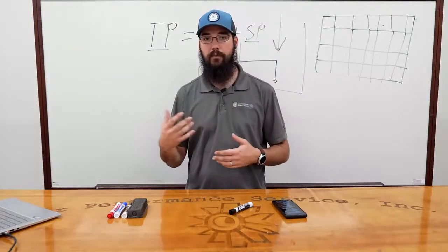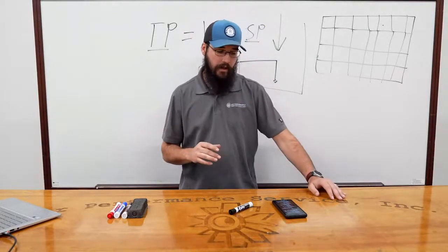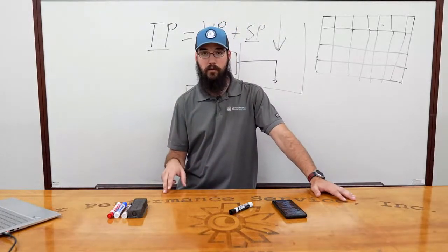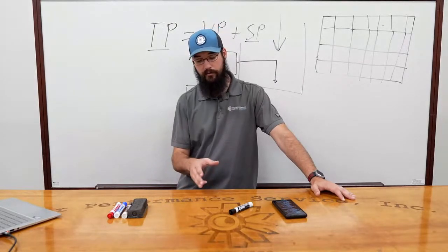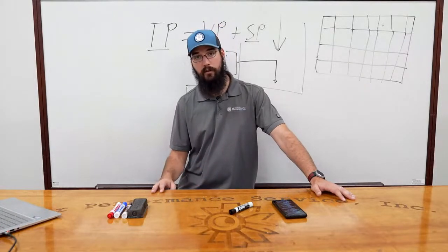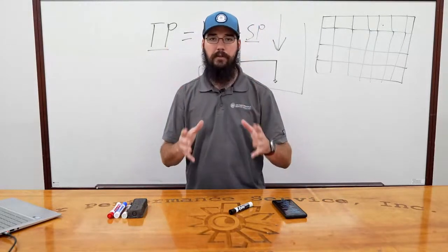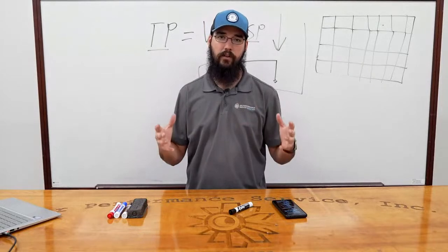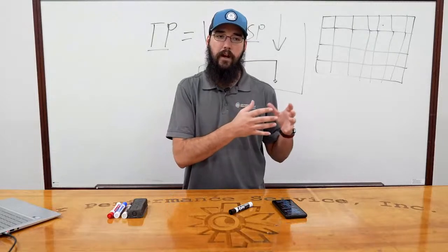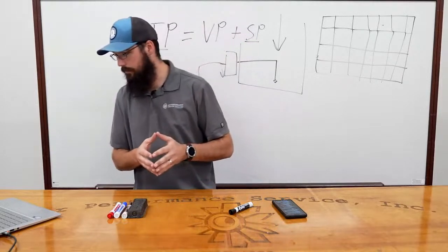You could also have it with load. You may have a lower load issue in a completely different scenario. From there, I might want to take a relative humidity and a dry bulb reading of my return, or just a temperature and a humidity reading. That way I can get a good picture of what my return load actually looks like. Those are quick readings that really narrow down the list of things that could be giving you problems. And a lot of the time, the air side of the system is the root of a lot of problems we have in systems.